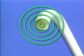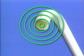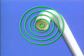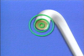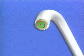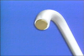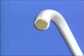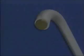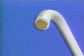After the current flowing through the conductor reaches its peak positive value, it decreases until it reaches zero. As current flow decreases, the magnetic field collapses. The motion of the magnetic field collapsing is opposite to the motion of the field building up. Since the motion is opposite, the self-induction is also opposite. The voltage that's induced in the conductor now has the same polarity as the applied voltage. When the magnetic field has collapsed completely, there is no motion, so there is no self-induction.